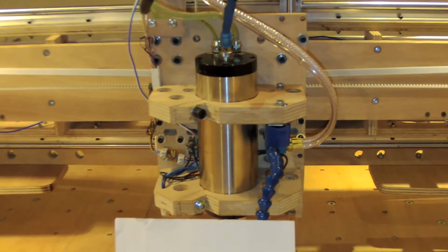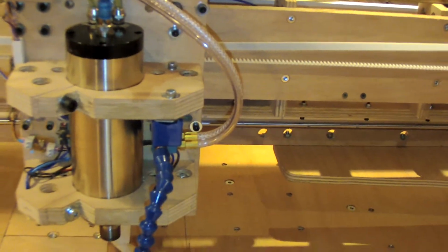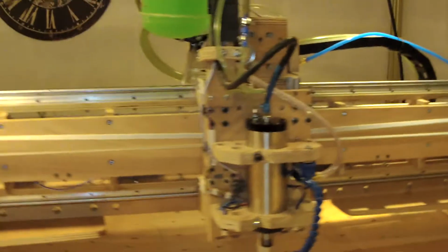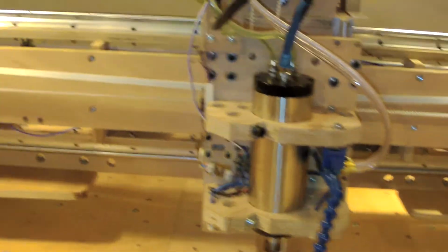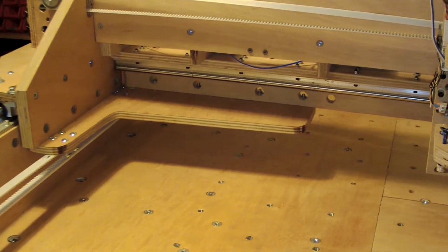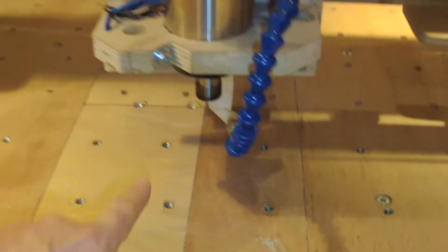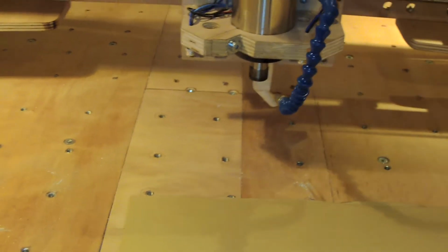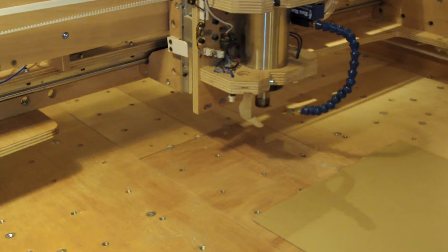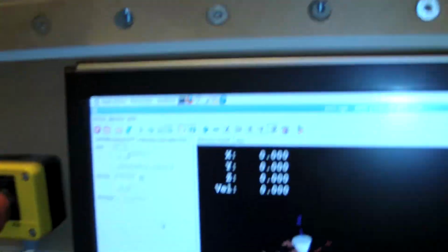So the first thing we have to do when you start with the CNC machine is to tell the machine where the 0 is for the X, the Y, and the Z. Some machines have what we call a homing switch that is able to do the work, but this one does not have a homing switch, so we have to do it manually. It means that the 0, 0, 0 has to be defined properly to make the milling of the stock. So in this machine, let's assume that this position is the X, Y, and Z 0.